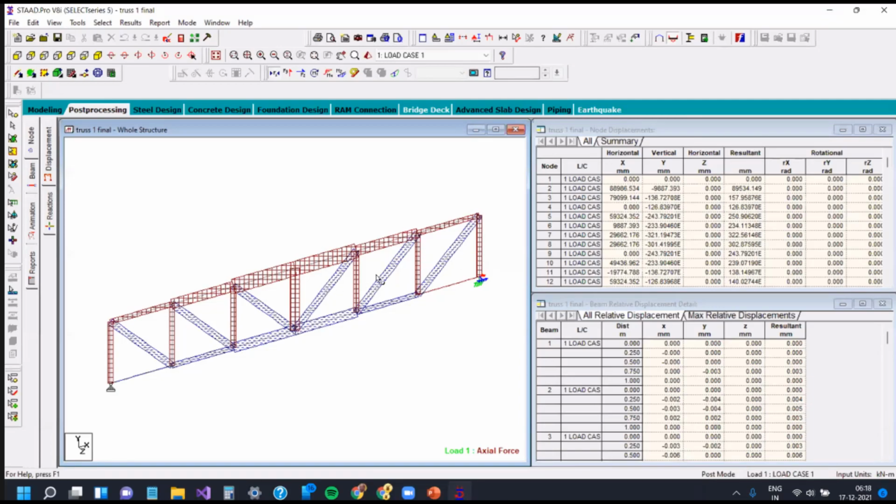However, the shear force is constant. On the left hand side, I may call it a positive shear. On the right hand side, I have negative shear. Now, all the inclined members are under tension. Why? Because I have reversed. This is called an N-type truss. I put the diagonal left to right, and then on the next half, I have turned it right to left. Now, if I had continued left to right, left to right, left to right, you will find all the other members will be under compression.